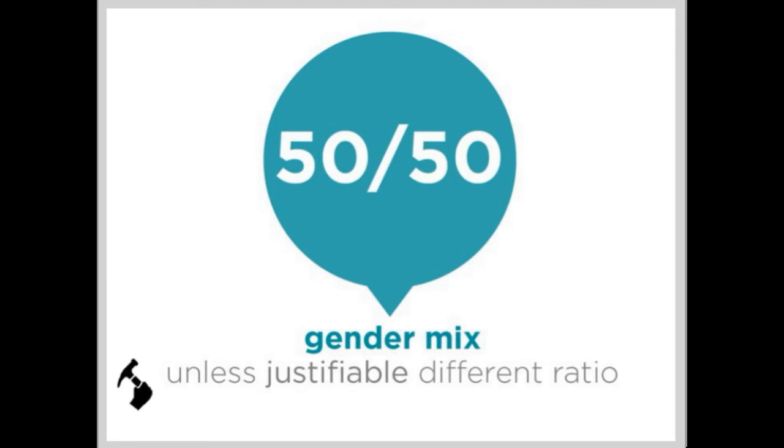Gender ratio affects water usage only when urinals are installed. If the project does not include urinals, a 50-50 or 0 to 100 male-female ratio should yield the same usage results.